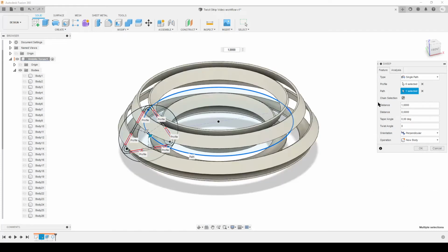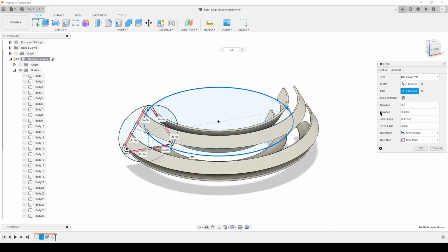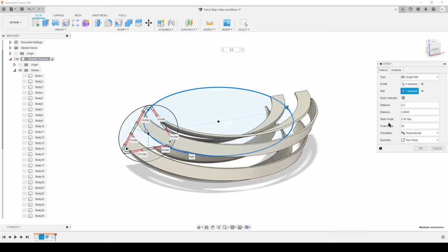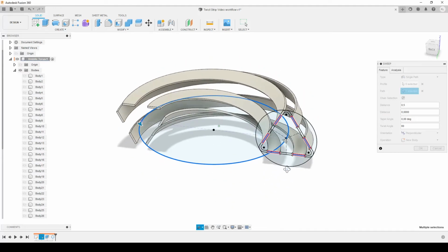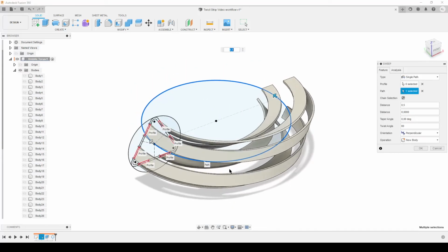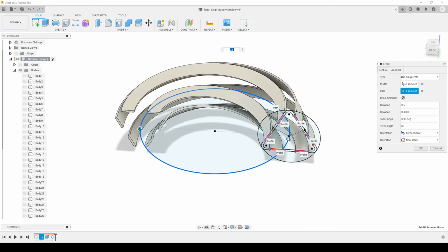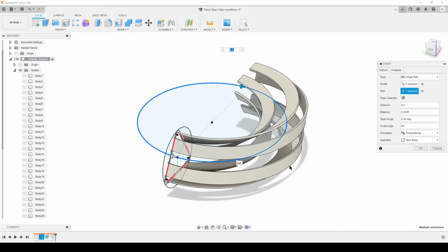What we can do now is change the sweep distance here to 0.5, so it goes half way. Because we're going half way, we only do 60 degrees of twist angle. So we're going to do it like that. Of course, we can do this sweep first, then do a second sweep with 0.5 here. But we can also set the second dimension here.